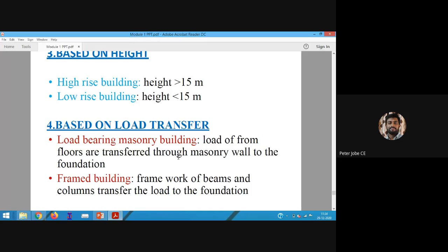If we take the data from earthquakes, we'll notice that casualties are higher for people dwelling in load-bearing wall structures than in high-rise buildings. That means casualties are high in small buildings, because they might be constructed using load-bearing walls, which are not sufficient in resisting earthquakes, winds, and other horizontal forces. So nowadays we are using frame buildings.